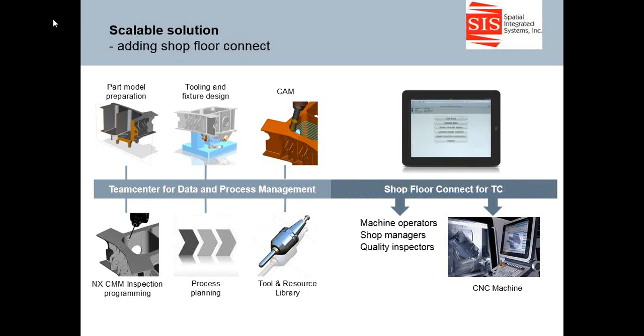Now, Shop Floor Connect from Teamcenter provides a means to connect easily and effectively to the centrally managed plan data. It supports a direct connection to machine tools and related equipment on the shop floor from the central database. For example, you can load CNC programs directly from the data management system into controllers and maintain data and process control. The simple web interface enables users to easily select released revisions.